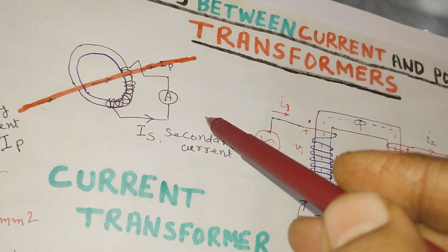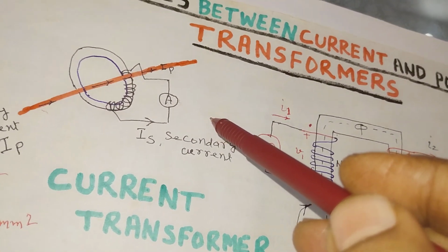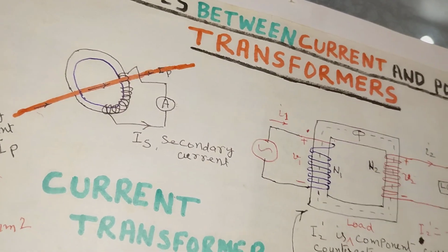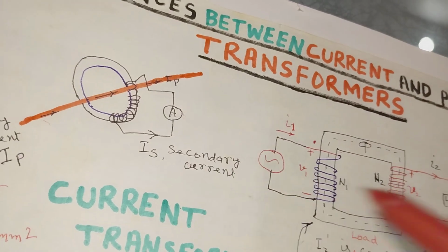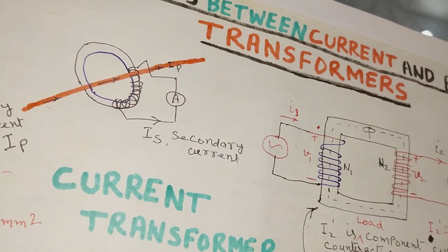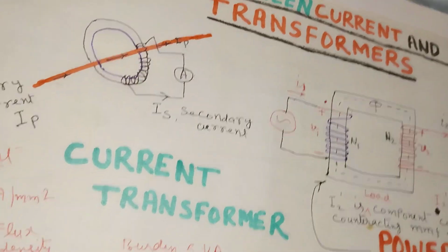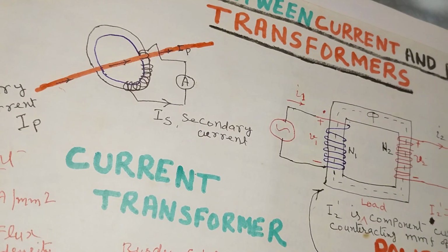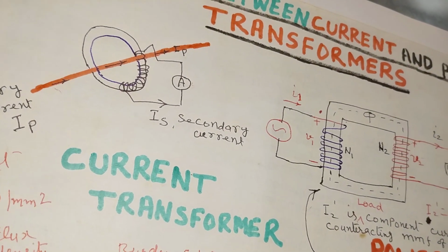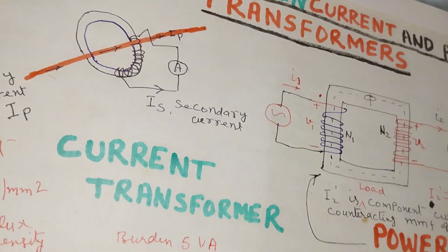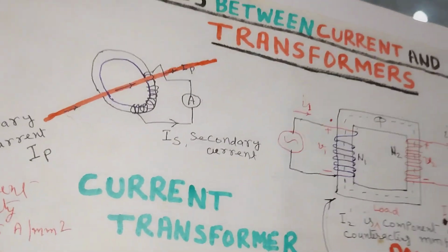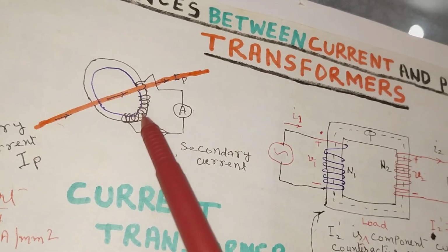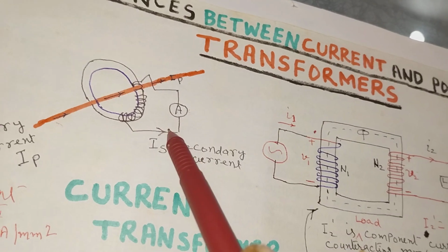Modern smart meters are composed of static elements. They carry very few milliamperes of current, but the current is rated for minimum 5 ampere. You might have seen the rating of 5 to 20 ampere or 10 to 60 ampere. So this much current, 5 ampere or 10 ampere, cannot flow through the static circuit. So in order to reduce the current, CTs are used inside meters.